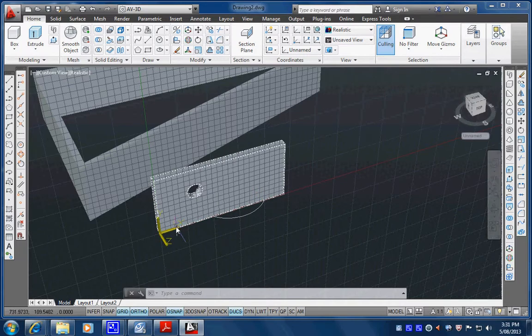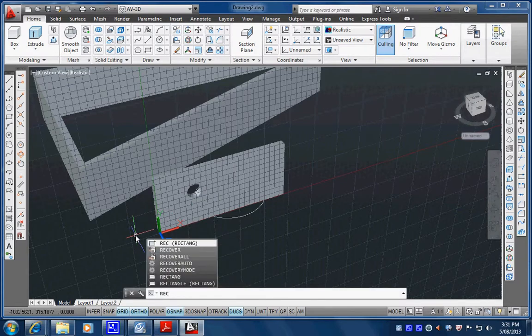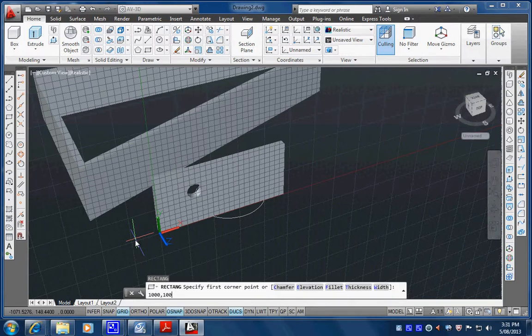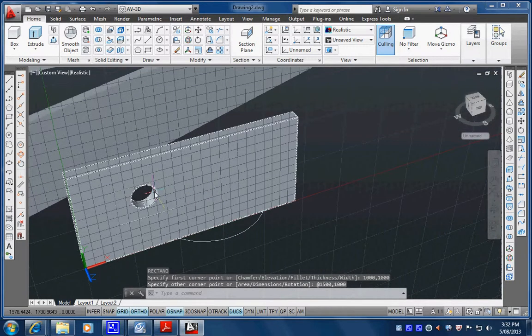So now I can, for example, if I know my window is, say, 1 meter in and maybe 1 meter up, and it's a certain length, I can actually do that. I can draw a rectangle, and I'm just typing it in this instance, rec, and I'm going to go, well, it's 1 meter in, so it's 1,000, for example, comma 1,000 up. Right, so starting from there, so there it is. And over this way, I'm running into that, but that's fine. I'm going to go 1,500 in the X. So at 1,500, comma 1,000 again. So make it 1,000 tall. There it is.